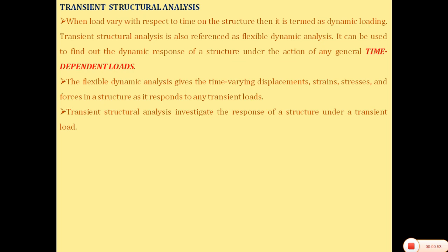So the flexible dynamic analysis provides time varying displacements, strains, stresses and forces in a structure as it responds to any transient load, which means that whenever we use transient structural analysis, the ANSYS solver gives us the displacement, strains, stresses and forces which are changing with respect to time. On the other hand, when we solved the static structural analysis, the load was dead, it was not changing. That's why it is called static structural analysis.